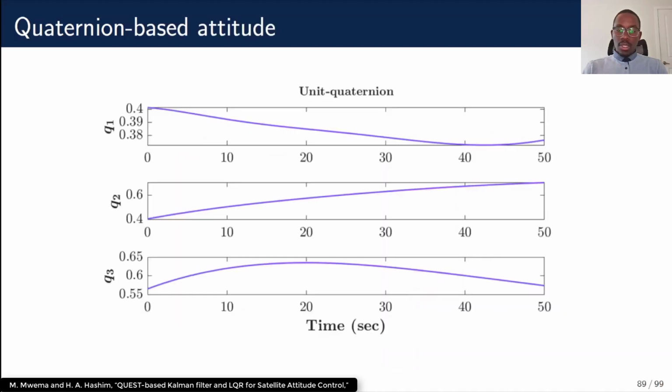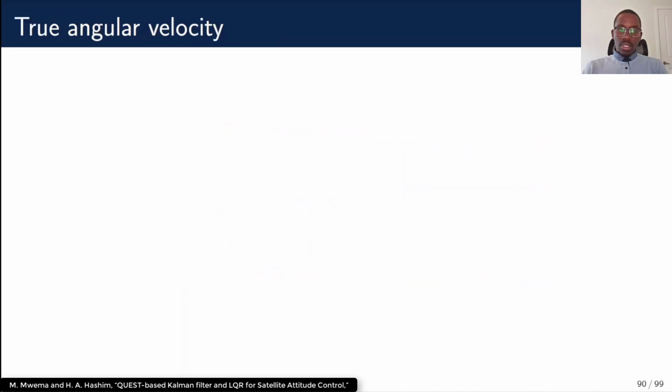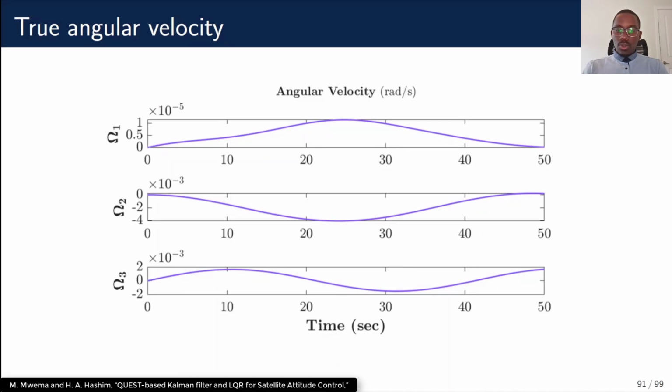The quaternion-based attitude simulation results are shown below. As can be seen, the steady-state error remains minor with the same Kalman filter initialization values, thereby illustrating the effectiveness of the controller in making quaternion attitude and angular velocity approach the reference values that were shown previously.